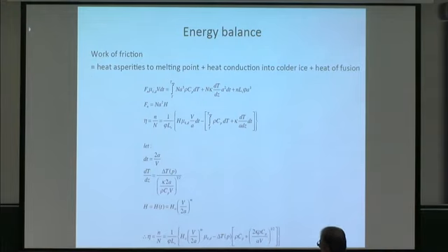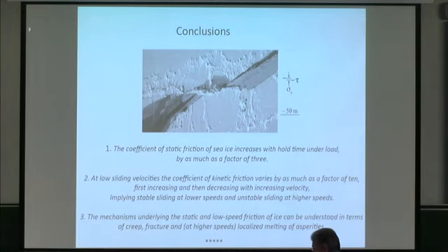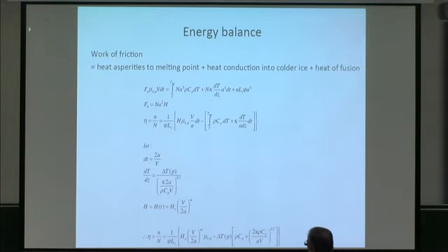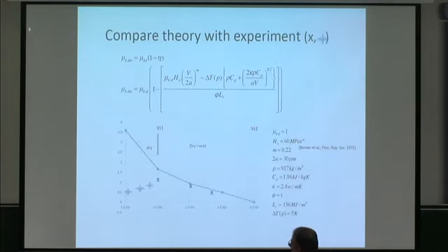And then one more time, if you let the time of contact be related to the size of the asperity and to the velocity, and make some assumptions about the thermal gradient in terms of the thermal conductivity of the material, then you end up with a relationship for this fraction of the asperities that have melted in terms of the parameters of the problem, including the velocity of sliding. And so this is what one gets. This is the first order crack at the problem.